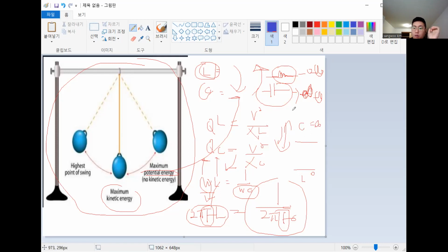Depending on the frequency value, if it goes up, the C reactance goes down, and if the frequency goes up, the L reactance goes up. We meet at some point. When it's the same point, that's it: we say that is the resonance frequency. Let's move on here.